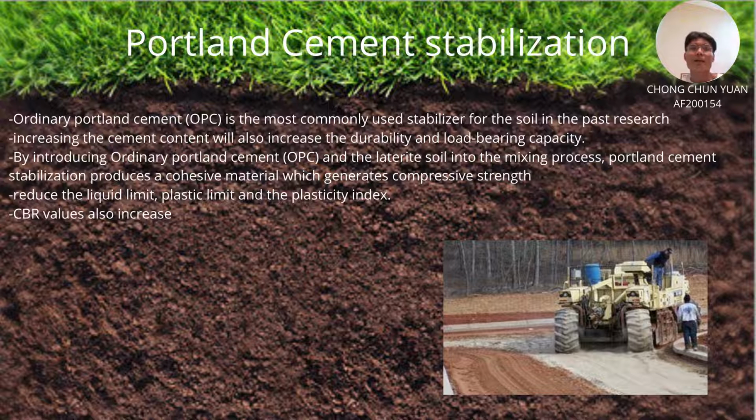From some of the tests, we can find that the liquid limit, plastic limit, and plasticity index were reduced, and the CBR value also increased by introducing ordinary Portland cement into the lateritic soil. It can be concluded that Portland cement stabilization will enhance the soil properties.